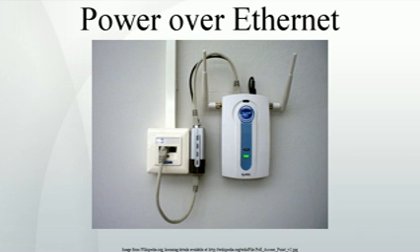Terminology. Power sourcing equipment. Power sourcing equipment, PSE, is a device such as a switch that sources power on the Ethernet cable. The maximum allowed continuous output power per cable in IEEE 802.3af is 15.40 W. A later specification, IEEE 802.3at, offers 25.50 W.